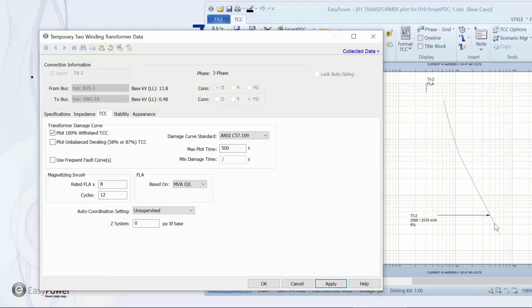The bottom part of the curve is due to mechanical damage. The higher current will cause potential damage to the windings, either because of the inrush shock and torquing the windings, or just overstressing them so that they have mechanical damage.